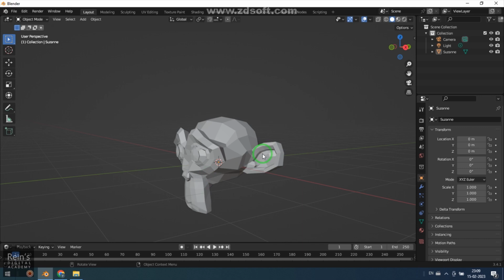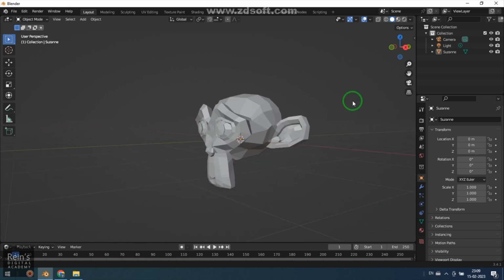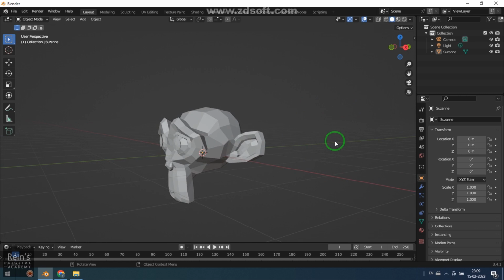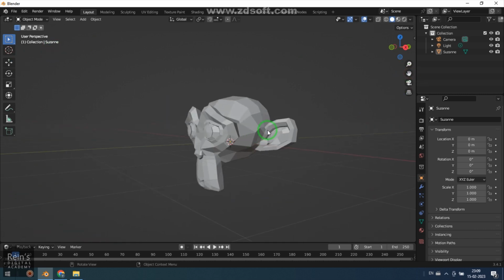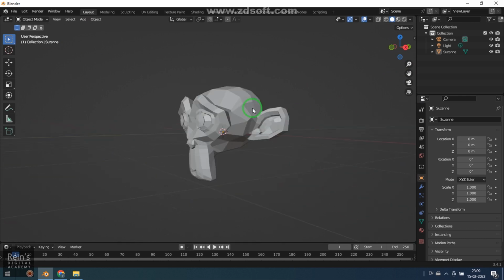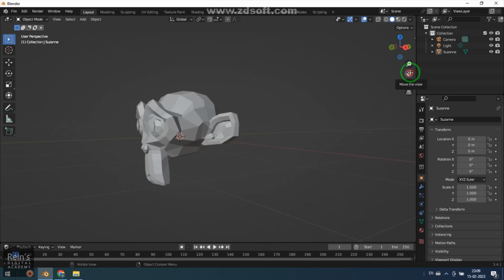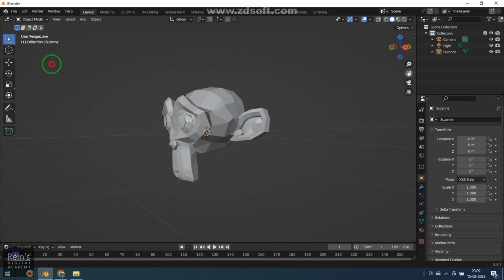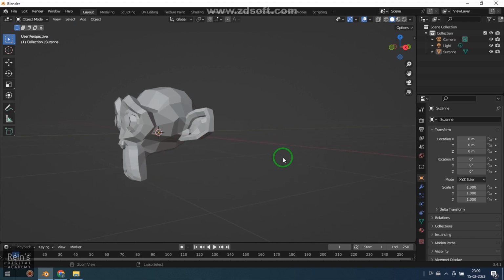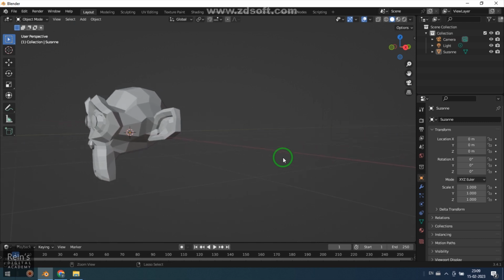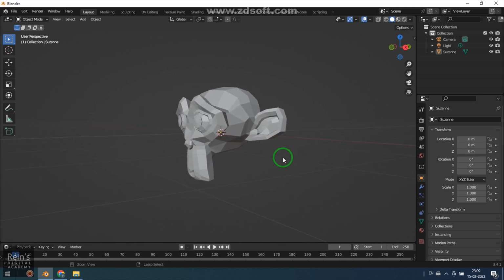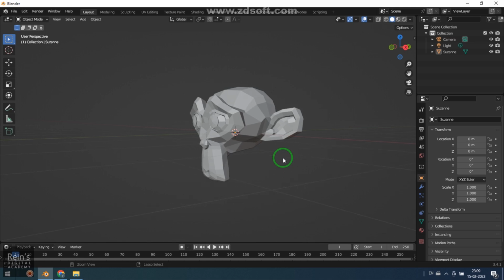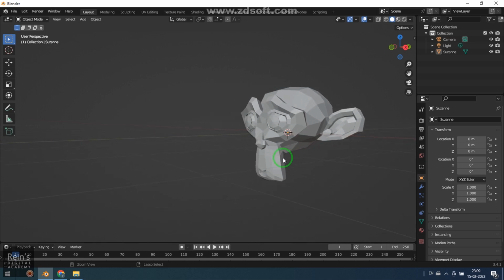I'll use Shift plus middle mouse button to pan. I can also use this hand icon here to pan. So there are two different ways I can do it. Shift middle mouse button is one, and holding this hand button is the other. I can also use Control 6 to incrementally pan to the left. Control 4 pans to the right incrementally. Every time I press, it goes one step. So I'm continuously pressing like that.